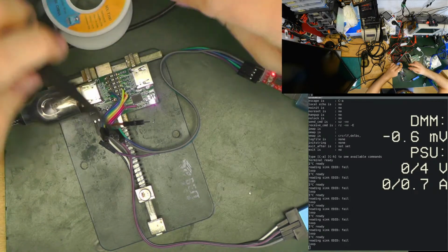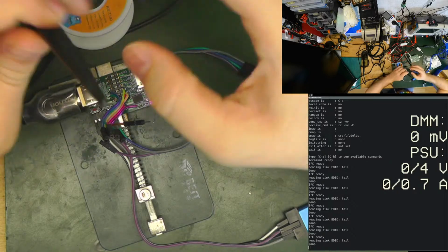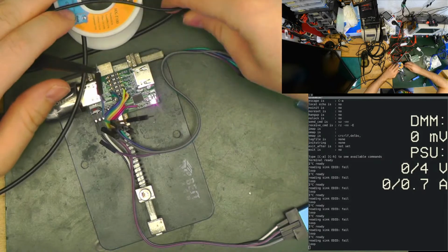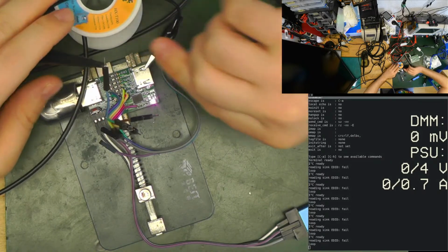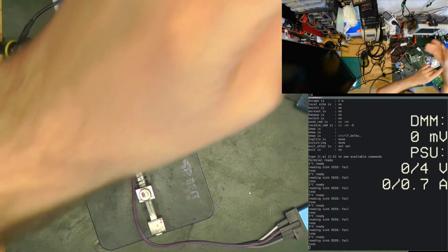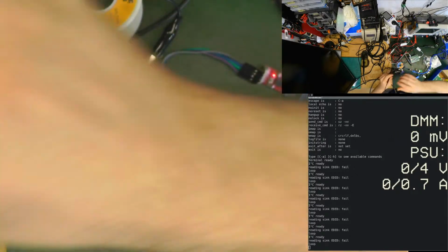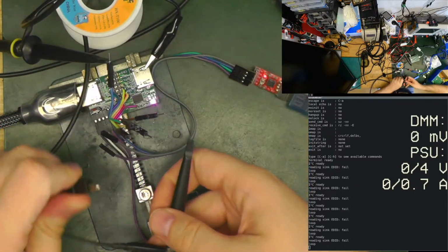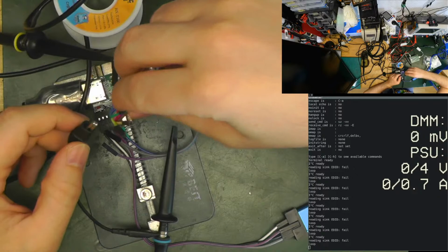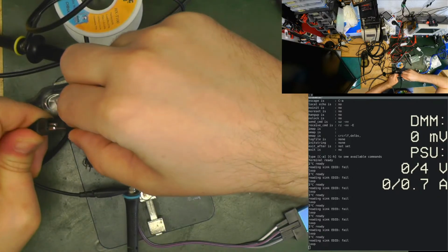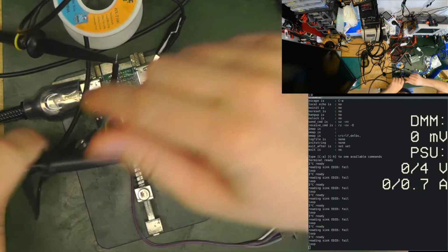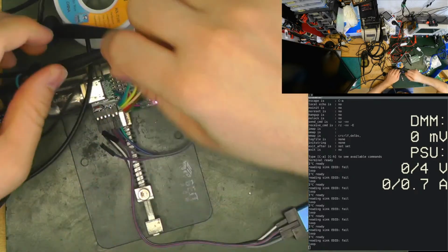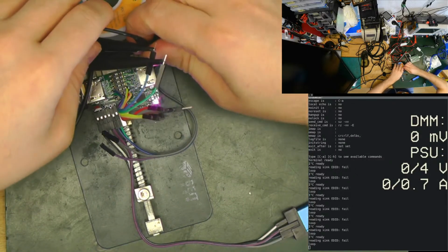And now we will test why. And that's what we want to do. So we are on these two lines. This is I2C. This is ground. The shell of HDMI is ground. That's one line. The other line is green. Let's get the other line. For now, I want to check with the oscilloscope and not with the logic analyzer, because I want to see if the signals look good or not.